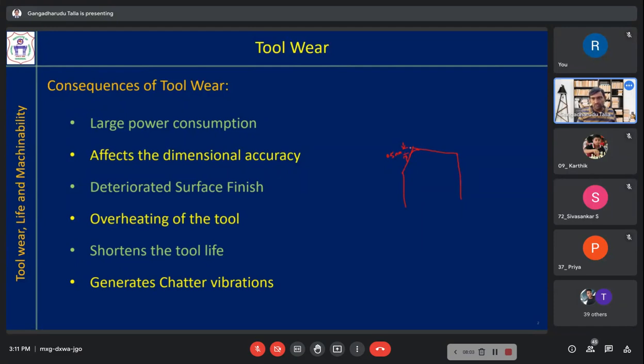So due to that, in this engagement, there is now a 0.5 mm difference. So the tool may now move in this fashion, an oscillating motion that will lead to vibrations and chatter. And of course, some more cutting force is also coming onto the tool, so that may lead to movement of the tool up and down. So more vibrations will be there.